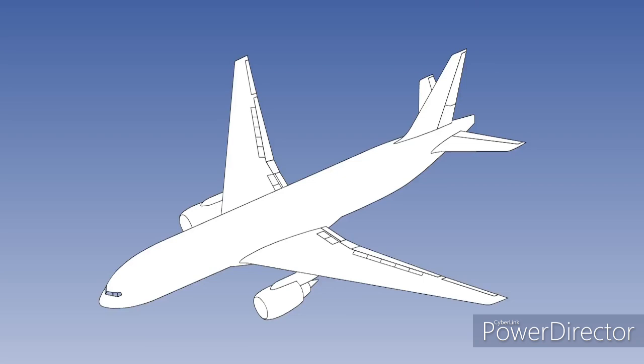Powered flying controls are hydraulically operated, either using a tapping from the aircraft main hydraulic system or alternatively using completely self-contained power packs. Powered flying controls can be divided into two categories: power-assisted and fully powered. We will start by looking at power-assisted flying controls.